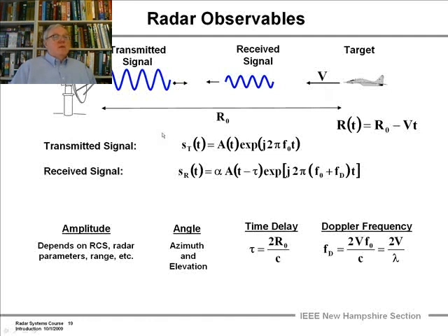And there'll be a received signal, the echo off the target, which scatters back and goes into the radar. The form of the transmitted signal is just this. Its amplitude is a function of time, and that would contain the information saying there was no signal before this time. And then we got this complex exponential signal. This is obviously one of the real or imaginary components. And it's on for a while, and then contained in the A of t would be that it's 0 afterwards.